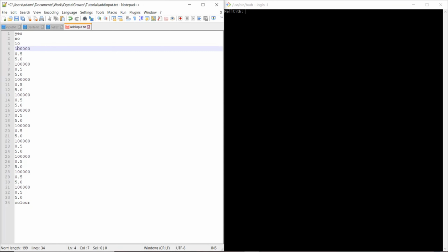We know we wanted the first period to end at 100,000 steps, the second one at 200,000, 300,000, 400,000 and so on, until we reach our final period. The final period is slightly different because we don't need to tell CrystalGrower when it's going to end, because it just uses the number of iterations of the program to define the final period's ending point. So we can get rid of that line.